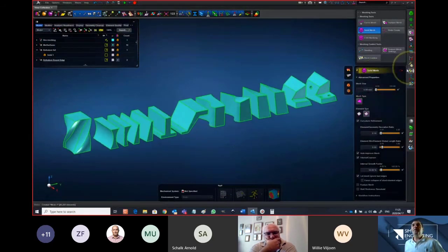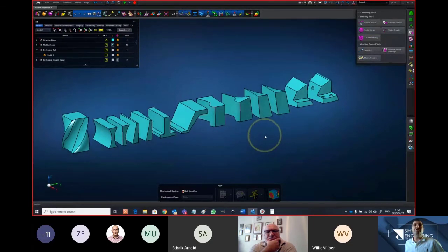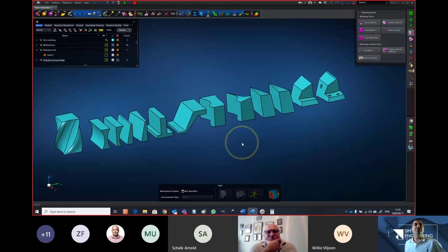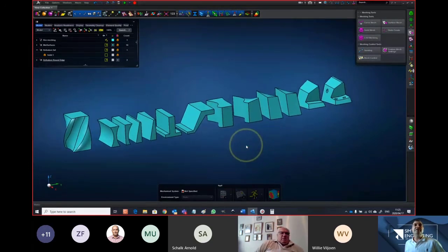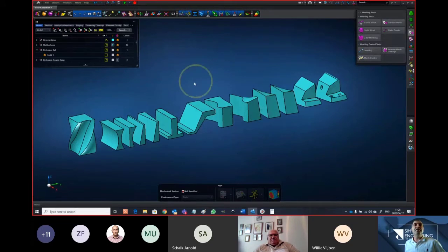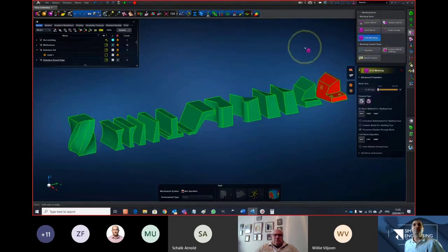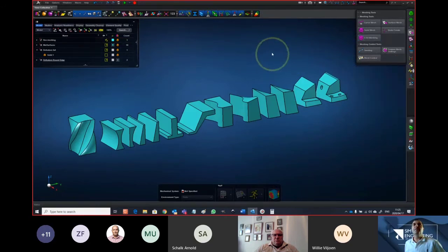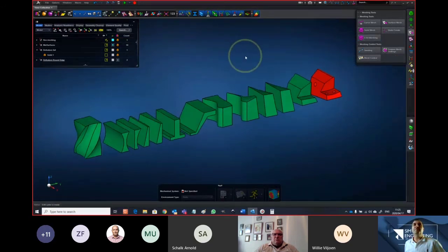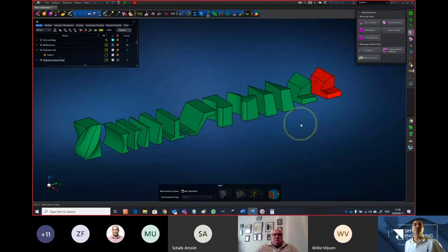And this is purely to show for those of you who are fairly new to Apex or who haven't used hex meshing before. The first step is to identify which items are hex meshable and which aren't. Now you can either enter the hex meshing tool and they will automatically be recolored red and green as to which ones are hex meshable and which aren't, or you can switch it on over here so that you have access to this in any other tool.